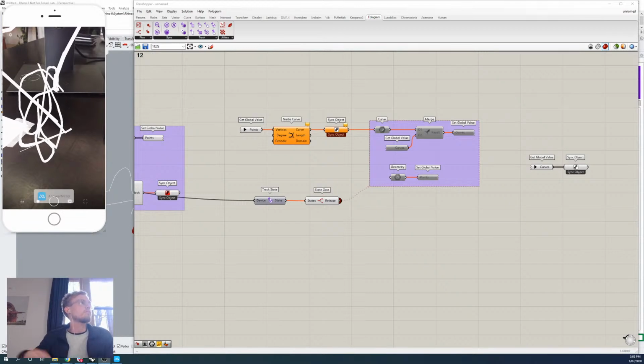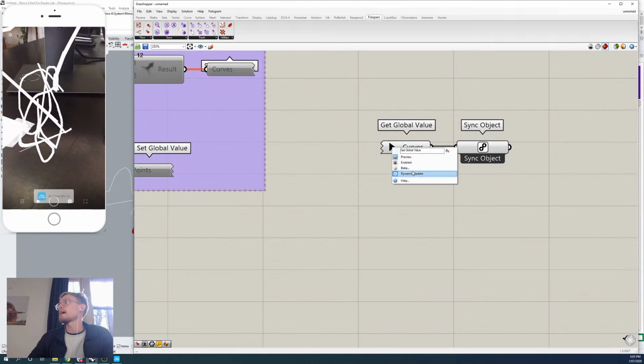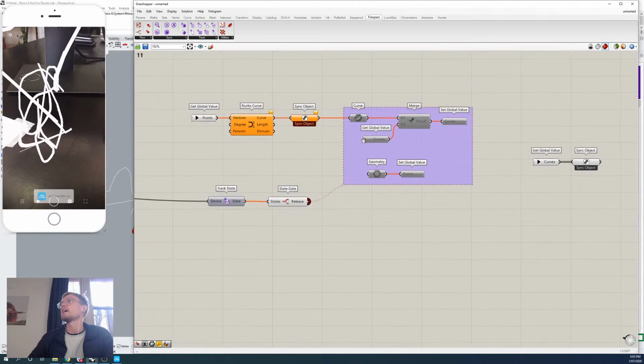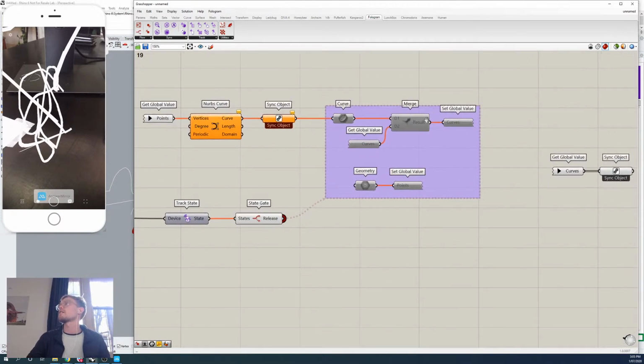Hi, Juan. So I see yours aren't saving. Do you want to just make sure that you've got this output set to another dynamic input? So just make sure that that's definitely dynamic, and then hopefully that saves it. Make sure that you have release typed correctly, because that's type sensitive as well, and you'll need it to be set to release. And you'll need these grouped, and then this connecting to the whole group, not just one of the components. So I'll zoom in a little bit closer just so everyone can have a quicker look.